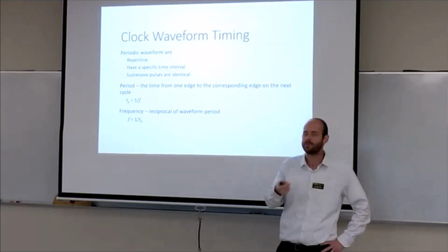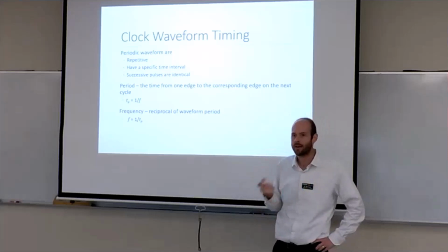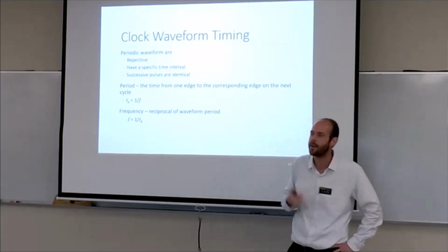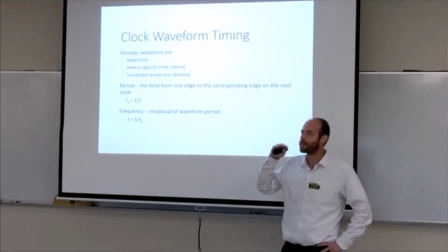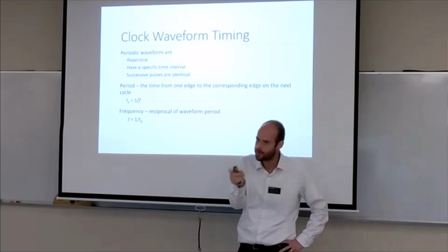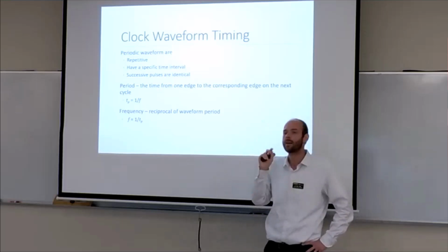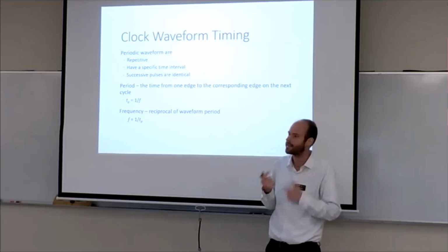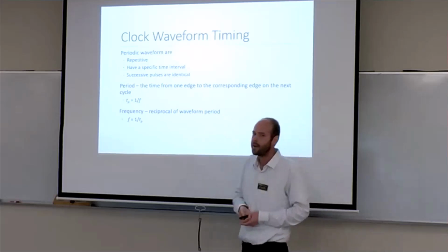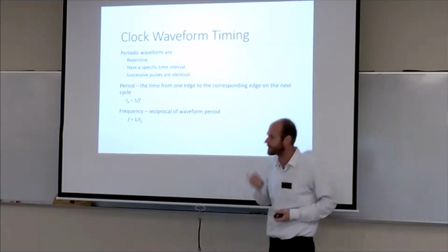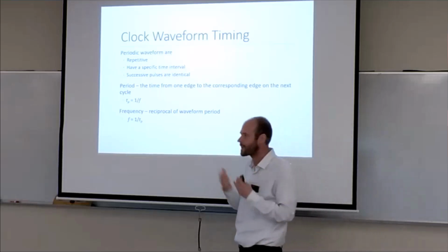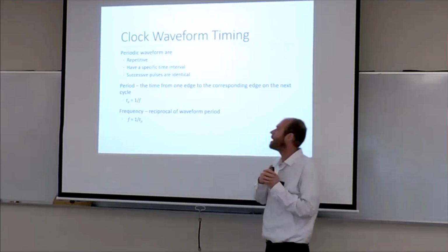It drove the action, but we did reference that 16 megahertz clock on a lot of our earlier boards we were working with. But the way it was used directly was pretty far under the scenes. We did directly use it when we talked about timers, because we had a prescaler where we could divide down that 16 megahertz and get slower ticks of our clock. That was one instance of interfacing with the clock, but we're going to be using clocks in a lot more dynamic ways in this class.